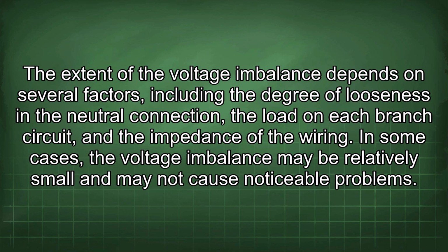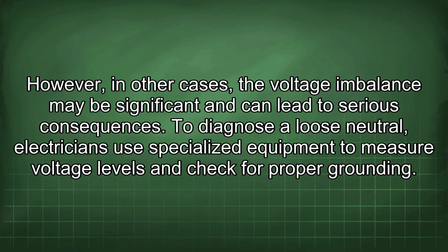The extent of the voltage imbalance depends on several factors, including the degree of looseness in the neutral connection, the load on each branch circuit, and the impedance of the wiring. In some cases, the voltage imbalance may be relatively small and may not cause noticeable problems. However, in other cases, the voltage imbalance may be significant and can lead to serious consequences.